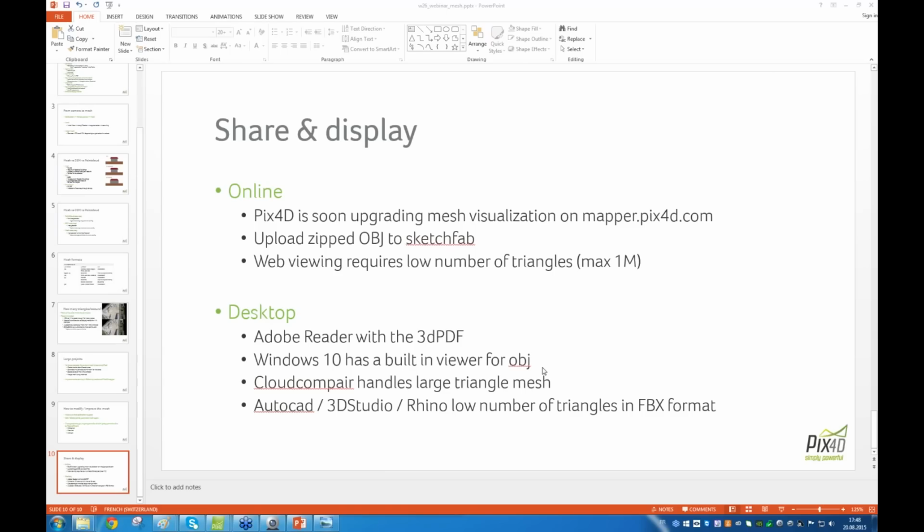Okay, now another question about Pix4D Mapper Mesh. We actually have an edition of Pix4D Mapper that goes up to the mesh, but doesn't allow DSM and orthomosaic export. The mesh version of the software already works with any DJI or any type of imagery. So you can import any imagery in it, and the software will process it and produce a mesh. So the software is already compatible.